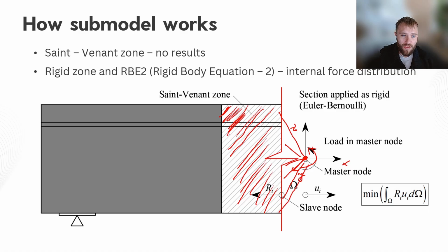There are some constraints, or rigid interpolations, that we call rigid body equations. Maybe you know it from Abaqus or ANSYS. It provides you rigid body behavior. So once you apply, for example, a bending moment, what will happen is that this part will be rotated like that. This point stays in the center of gravity of the section, so this is my rotation. Also, the shear forces are applied equally at the end of the trim zone.